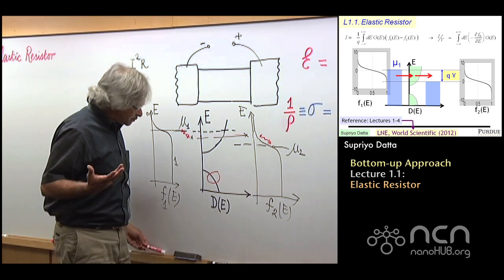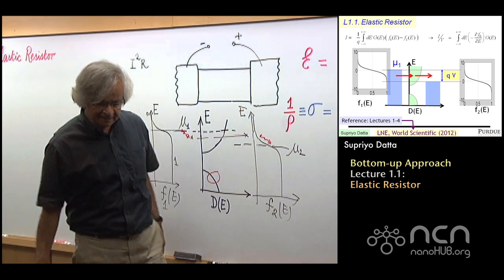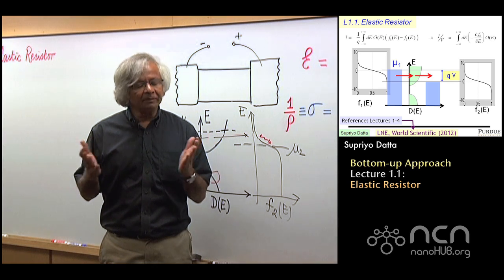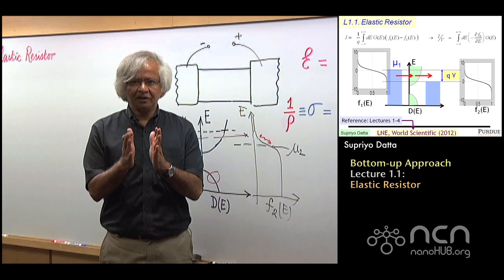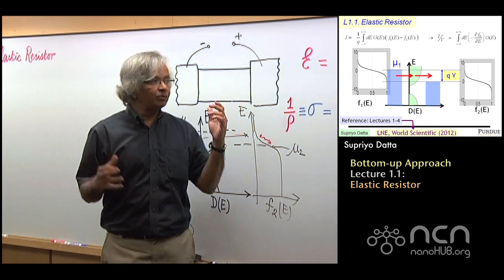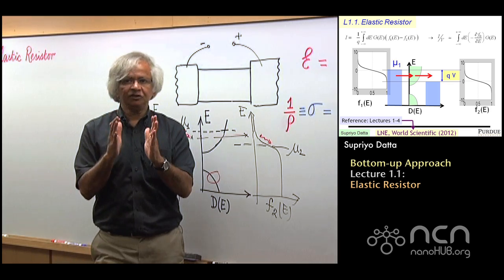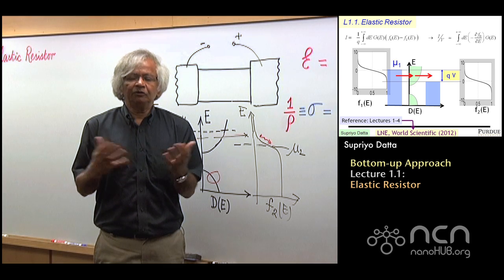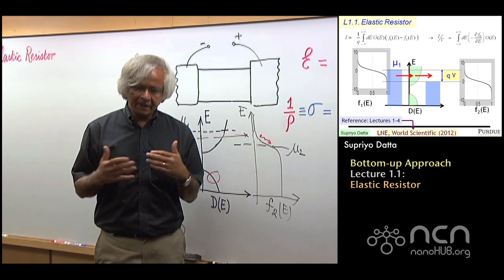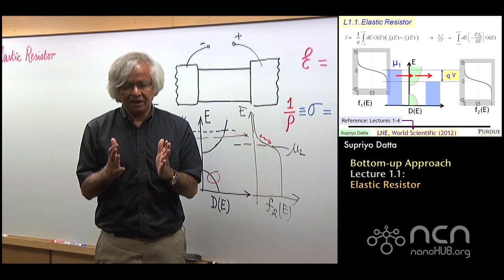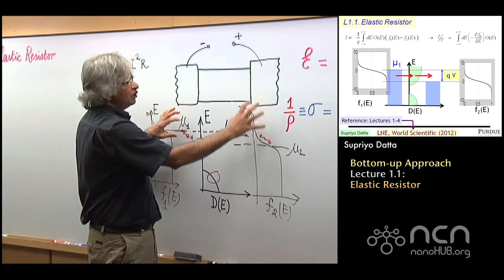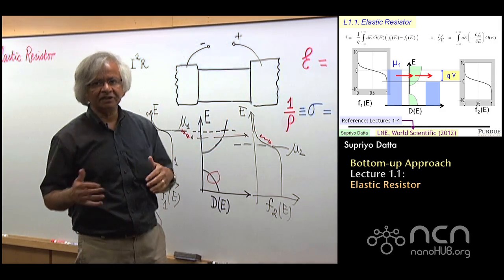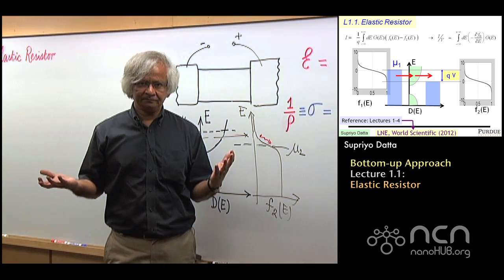And I'd say there is experimental evidence for this, in the sense that what people find is when they apply voltages across small carbon nanotubes, if all the I²R heating were actually occurring in the nanotube, it would have burnt up. And the feeling is the reason it doesn't burn up is because a lot of the heating is actually at the ends, which are large contacts which can get rid of all that heat.